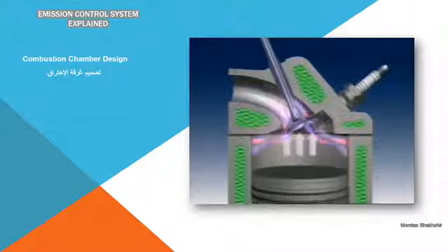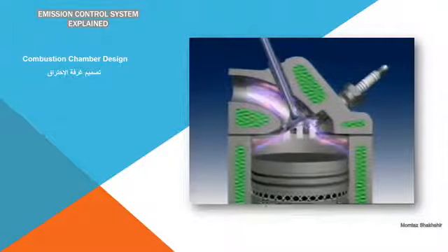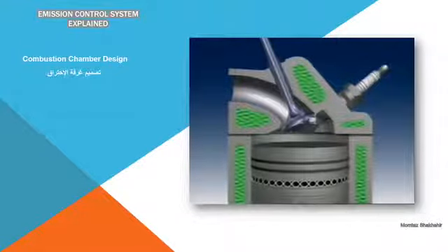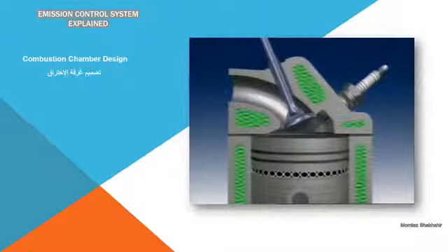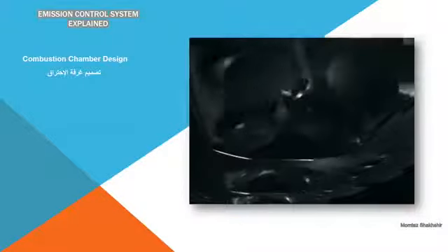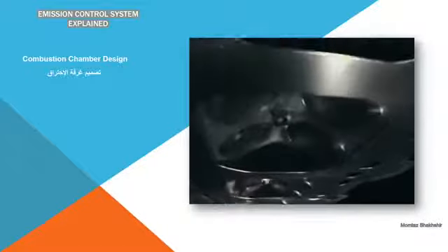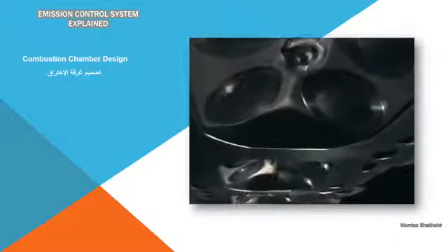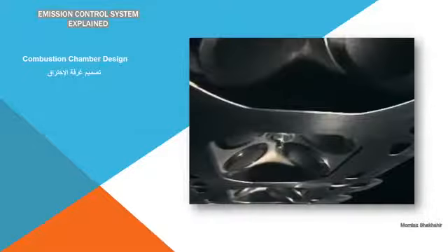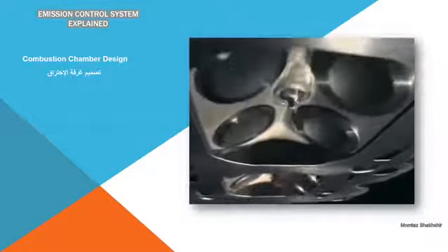If the spark plug is positioned so that the flame front travels evenly through the combustion chamber, combustion is more complete. Gas flow rate and volumetric efficiency can be improved by using 2 intake valves in each cylinder. The effective port opening is increased and the gas flow rate increases.